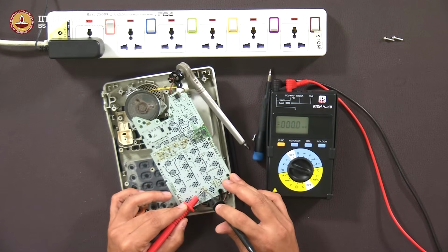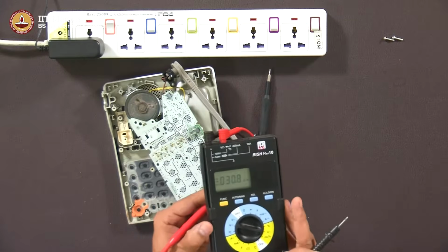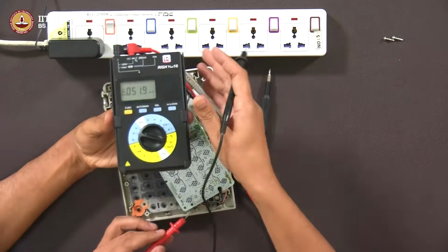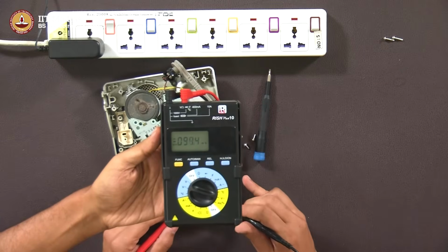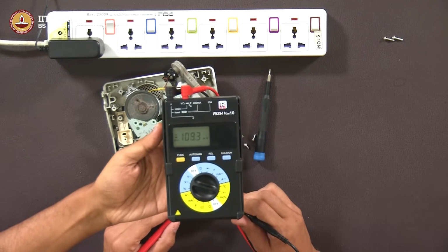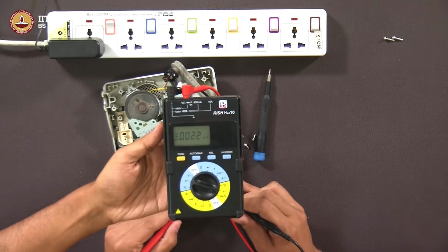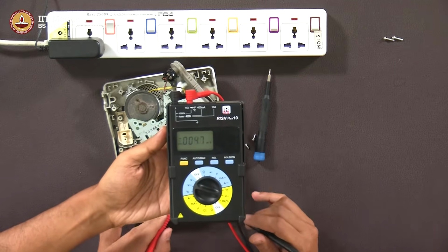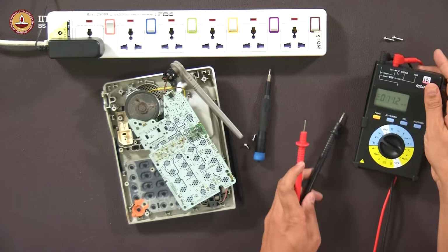Almost zero. You see that this voltage is, can you just hold this here? I'll place it again. It is sort of falling off to 1 millivolt, 2 millivolt, down to 0.9, effectively 0 millivolt. So there is no potential difference between these 2 points if I do not connect a power supply.